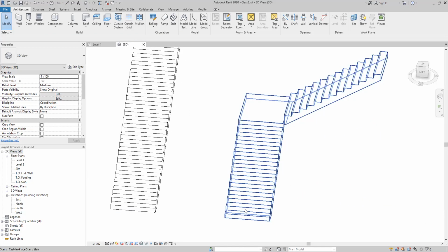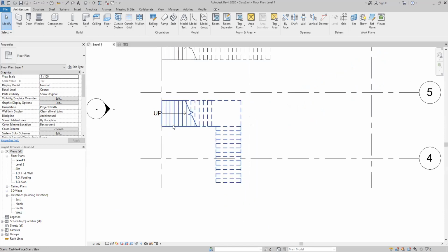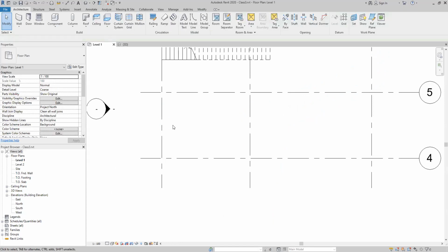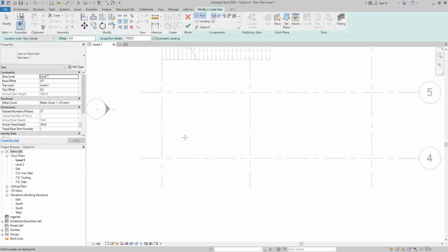Understand? So this is most of the time we do this kind of the staircase. Right? Normal our residential building or office building, we do this kind of thing. Okay? So this will become a mid landing. Okay. This is a one way to row the mid landing. There's another way to row the mid landing. Okay. Now let's see how to do the another way mid landing. Go back to the stairs. Right. This property same. I keep it same. So select our center line.